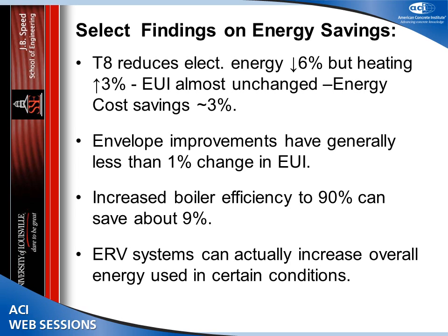We were kind of surprised by the results that suggested that the energy recovery ventilation systems that we looked at actually in some cases increased the overall energy use by the building. Tracing back down to try and understand that, it looked like the mechanical ventilation that we require by making it airtight and then requiring these energy recovery ventilation systems, the additional fan energy on that was more than compensated for the actual energy recovery.